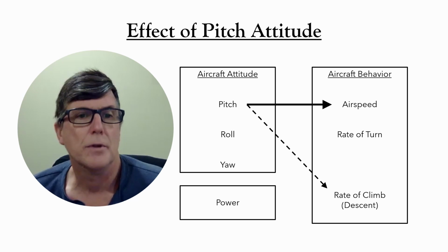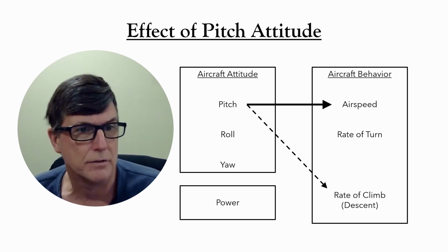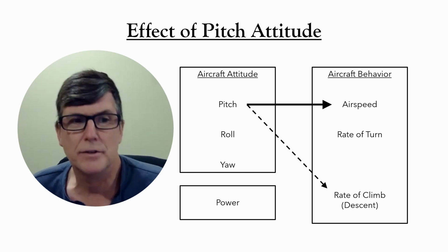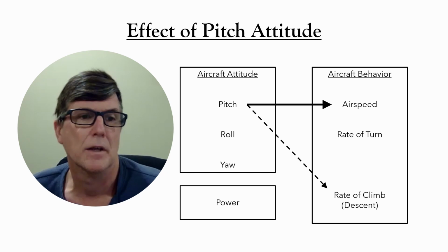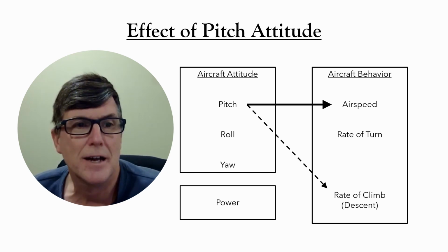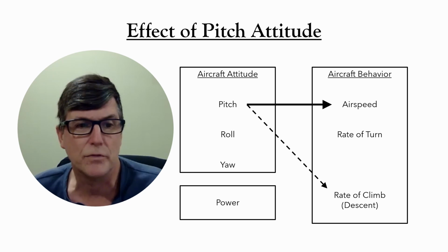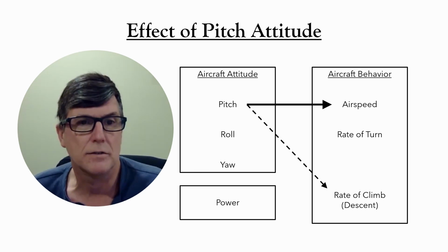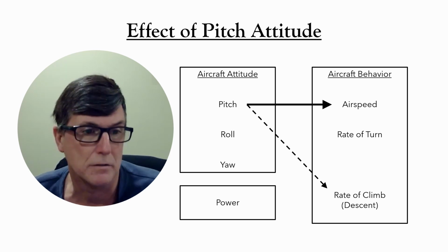In other words, pitch has a transient effect on rate of climb that's positive. But the lasting effect is positive at cruise speed and negative at low airspeed. I'm labeling the effect on climb rate a secondary effect because it only occurs in some flight conditions. Some people would object to calling this a secondary effect because it is strong in cruise flight.